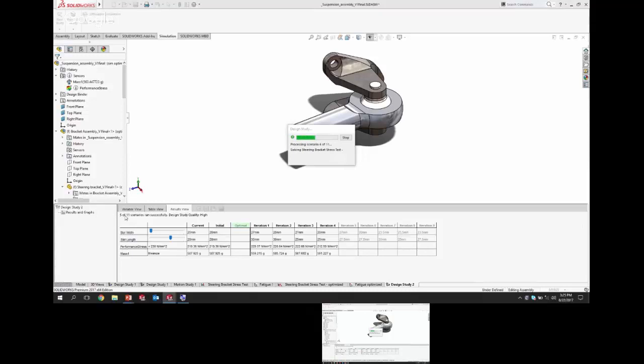So here's a place where having the model optimized makes a big difference, right? You could probably look at this model and say, well, is it really going to make that big of a difference if we turn off the fillets and turn off that SolidWorks text? For all intents and purposes, at least for my own personal feeling, it wouldn't really make a difference. But then I started to iterate, and each one was taking an extra 30 seconds. I might get really frustrated, and I might not be tolerant enough to wait for that. So I might want to put in 10 minutes of SolidWorks modeling up front so that I don't have to wait another 2 hours on the back end, just for machine calculation.